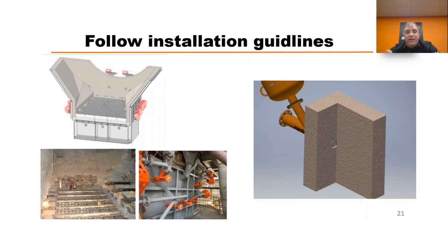The picture on the left is an FLS crossbar cooler. They design it in with different air cannon nozzles, from fan nozzles to some pipes, depending on what they're doing. But the thing about it is, a lot of times the cannon installation gets pushed off onto the guys that are putting in the refractory. They don't have a whole lot of guidelines. They aren't looking at installation manuals.